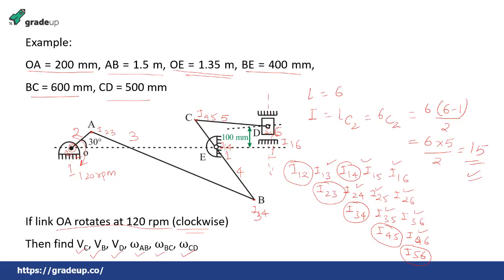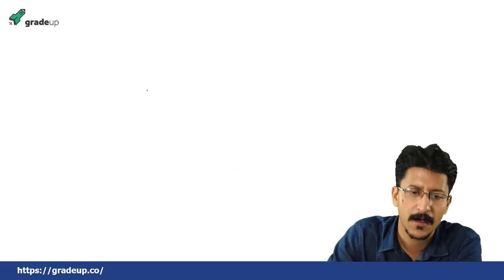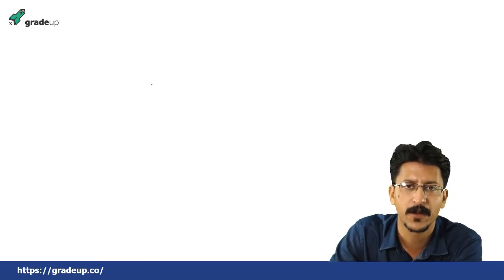Okay, so for this, let me tell you how to find these. First of all, please remember that this is a mechanism having 6 links. So how to find this? We draw a regular polygon with the number of sides equal to the total number of links. In this case, the total number of links is 6.